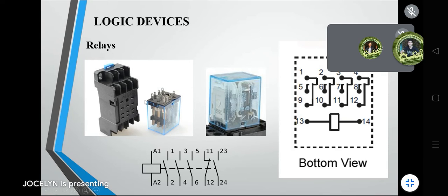Instead of having all those wirings and lots of relays to change the input to the opposite position, which will be another input to another process, and so many relays and wirings being used, we can remove all of these relays and wirings and instead use a PLC, program it there, and then no more relays will be needed.